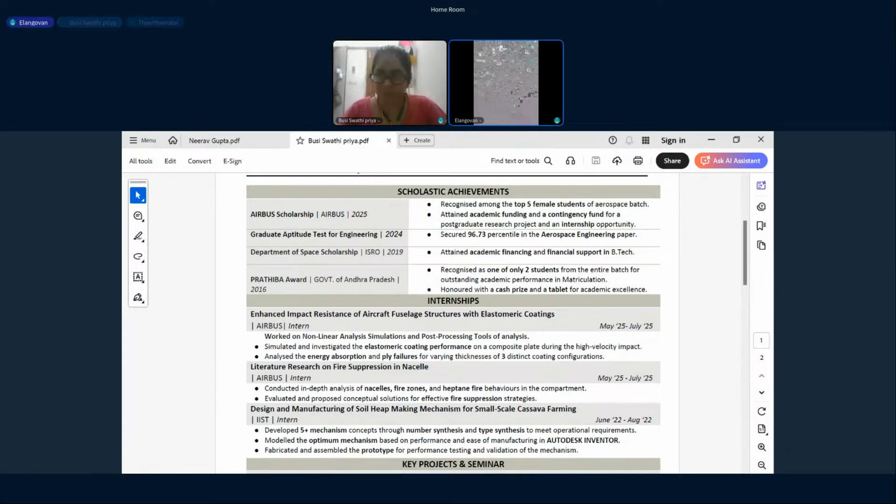Okay, add all forces: M x double dot plus C x dot plus K x is equal to 0. If there is no external force, then it is 0. This is called the free vibration equation. If it is equal to some external force, that is called forced vibration.